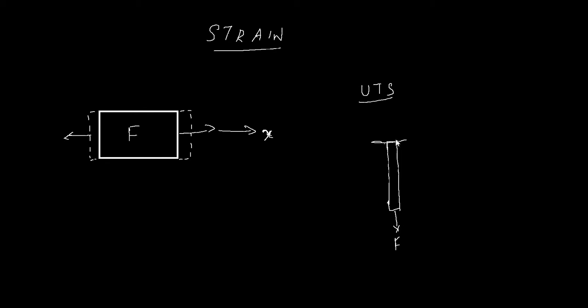So you apply a particular load, and you decide a length of the specimen in which you are conducting the analysis. Let's call this L, and you apply a particular load, and you will also have a recorder elsewhere that will measure the change in dimension. So for each load you apply, there will be an extension on this length. So say for example you apply a load of 100 kilonewton, then you have a change of delta L here.